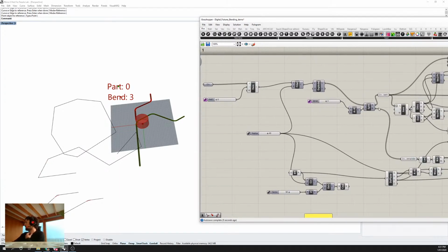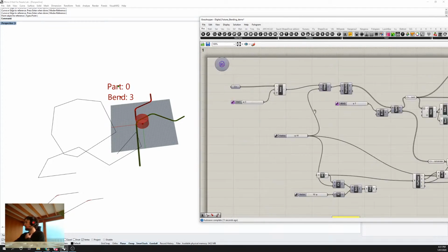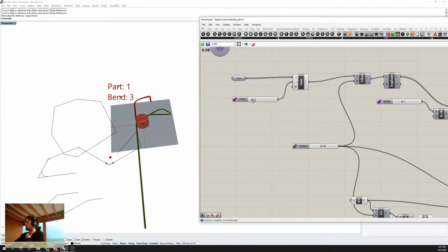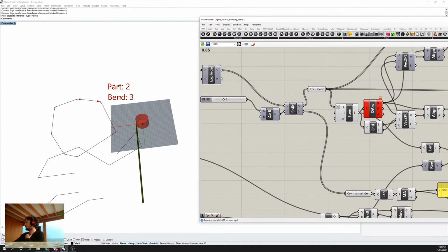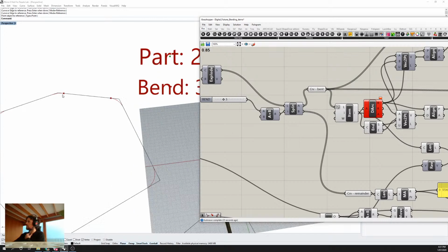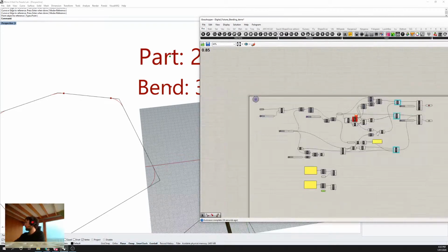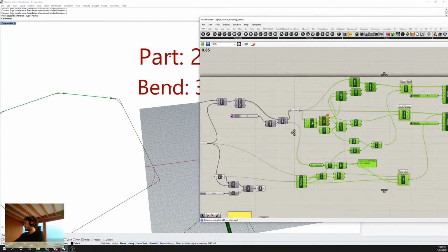All right, now debugging. So finding out why our closed parts work slightly differently. So as we split the list, we got 6. So with our closed part, the first line segment is actually an arc rather than a line, which is kind of interesting. And so with closed pieces, we actually don't want to reverse this list here, which is a bit of fun.